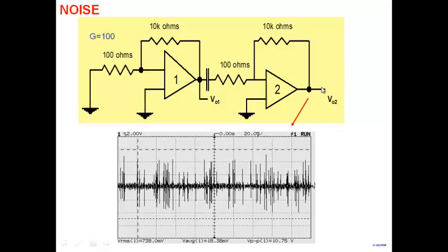Well, as I said, all the elements that you take, every resistor that you take here is a source of noise. Every transistor is a source of noise. The movement of electrons in a resistor is random in nature. The movement of electrons and holes inside a transistor is random in nature. There is randomness inherent in all the devices that we handle. Resistors, transistors, diodes, there's an inherent randomness in them, the way the carriers move. And they're all sources of noise.